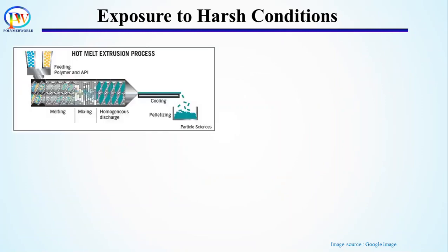The first step where a polymer experiences extreme conditions is during the extrusion process. Extrusion is performed well above the melting temperature of the polymer and at very high pressure and in air, which contains oxidizing agents like oxygen and metal. At such a high temperature and pressure, the bonds connecting the monomers are highly susceptible to oxidation by oxygen and metal. And if it is not controlled, polymers can degrade severely, which will make the final product very weak and brittle.